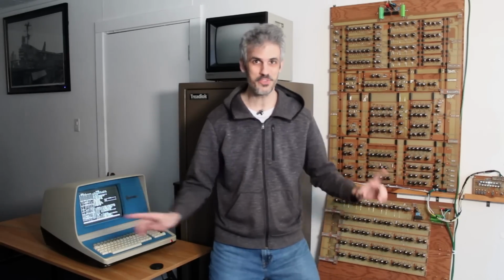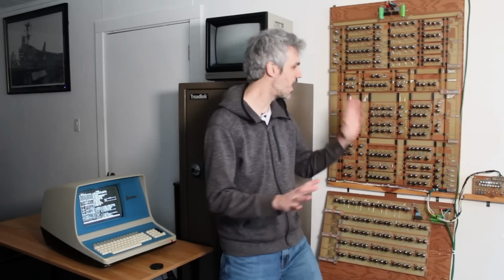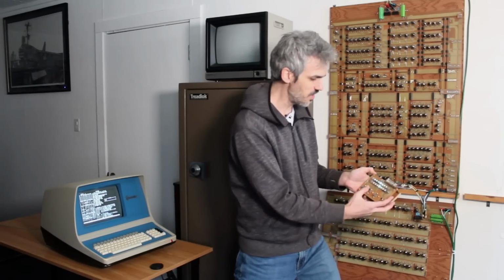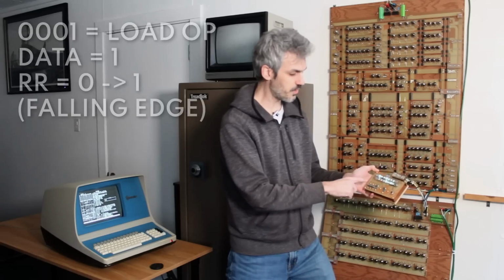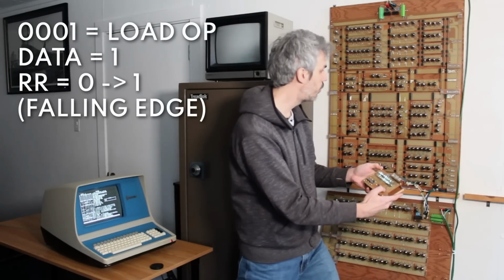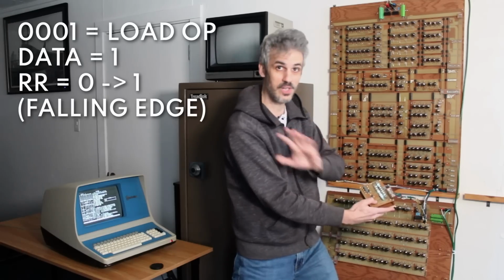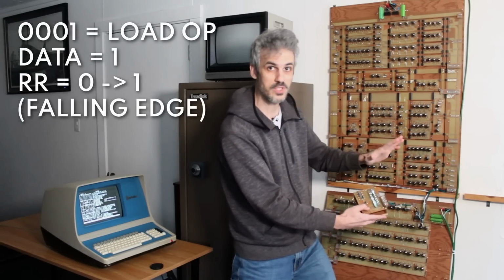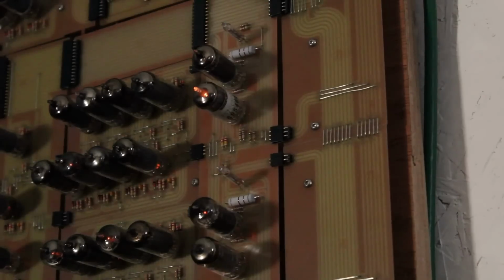So let's load 1 plus 1 on both systems and see how they react. So in order to do that, we will do a load operation of 1. So we're 0001 with the data set to 1. I'll push the clock, and when I push the clock down, nothing should happen. When I release the clock is when it stores the 1 in the result register. And yeah, I can see it did that.